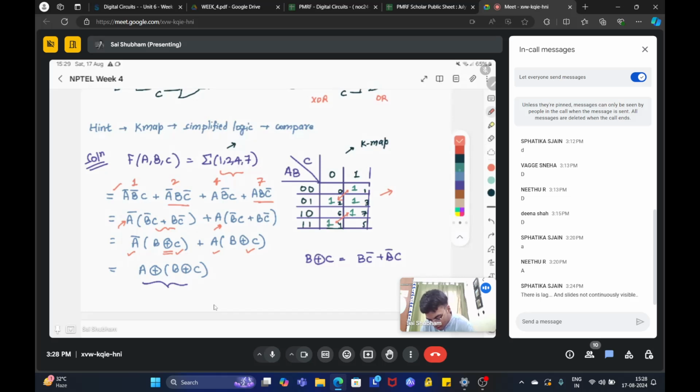So here we wrote down the logic. Okay. Now, if you look at these two expressions, I can take a bar as common. So now my expression will be a bar into b bar c plus bc bar. Okay. And we know that this is the XOR operation. B XOR C is represented as bc bar plus b bar c. So here I have replaced it with XOR operator. Similarly, here, as you can see, the expression has repeated again like a bar.